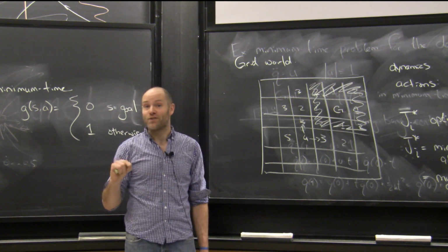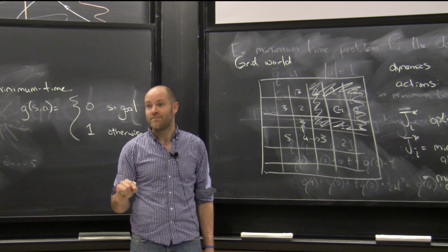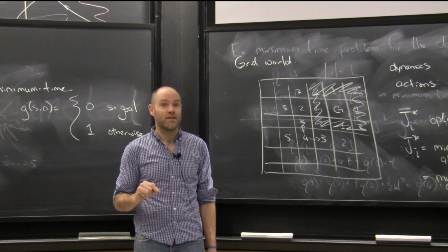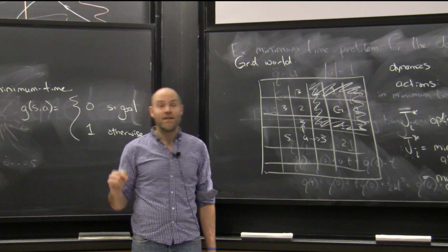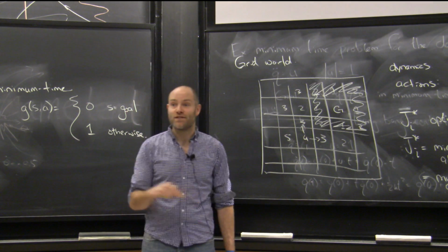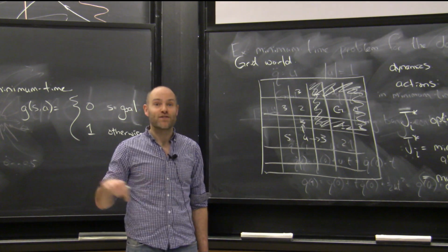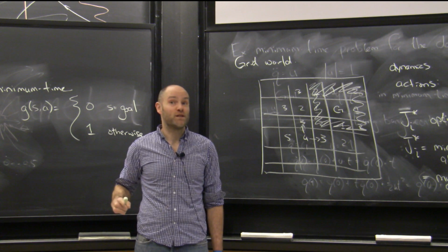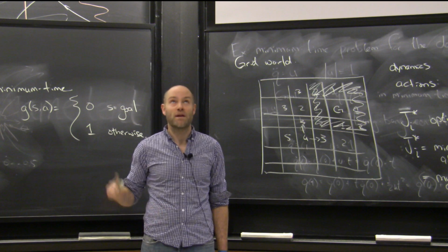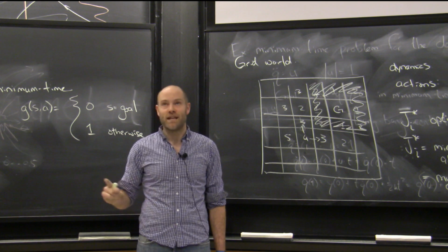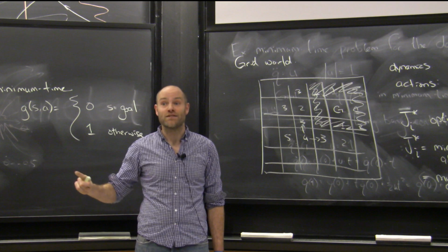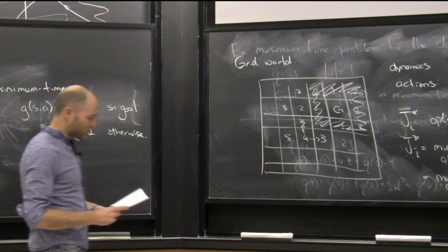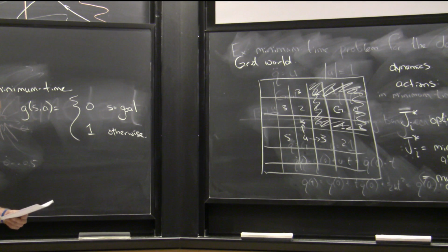It happens all the time, actually. If you have noise in your system, let's say any sort of random disturbances, process noise, then even if you get to 0, you might get bumped away. And in fact, if you integrate cost over time, you will accrue infinite cost. So you have to handle that case pretty specifically. There's a special trick for linear Gaussian systems: the cost to go of a linear Gaussian system is infinite, but it still has a closed form solution. That's a detail, a trick.